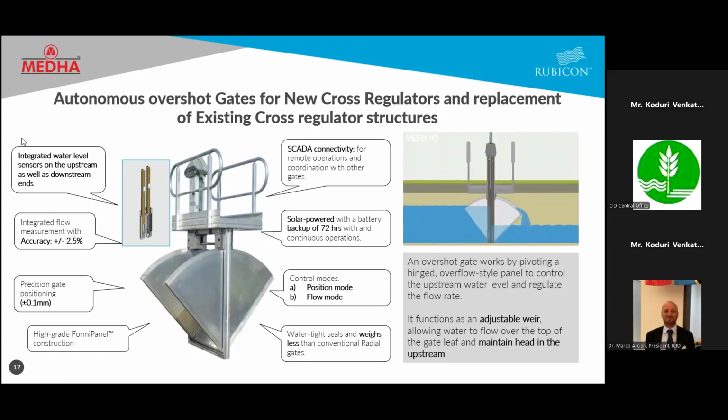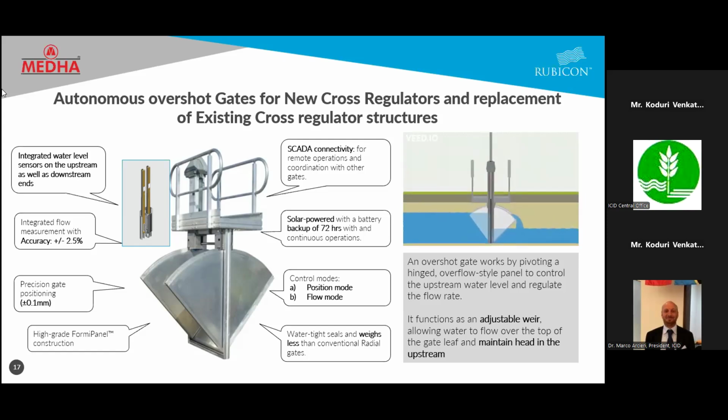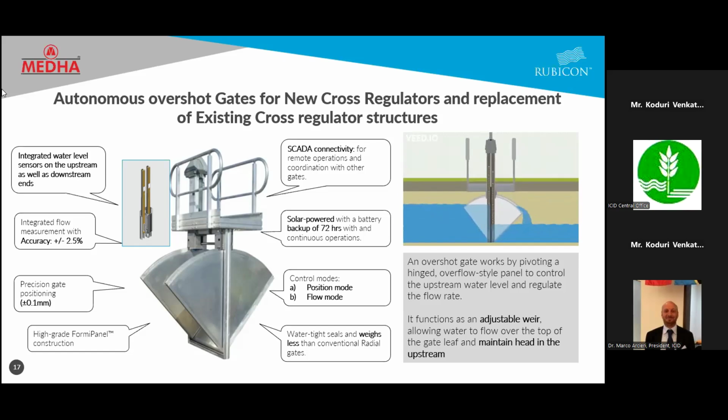And again, the quality of the material is marine grade aluminum alloy, which is certified across the major laboratories in Australia and India. The SCADA connectivity for remote operations and the coordination with other gates is also possible with this smart gate, where each gate comes with its own pedestal that has the capacity to talk to every gate independently via radio communication or GSM facility.